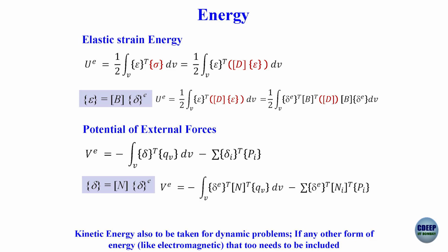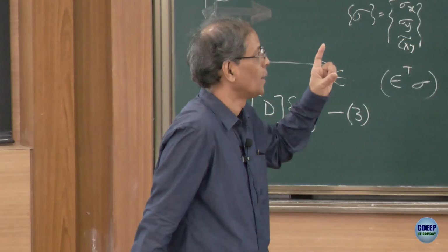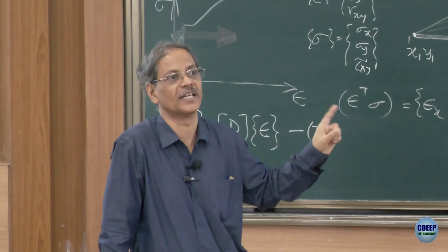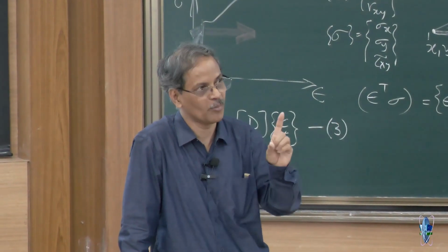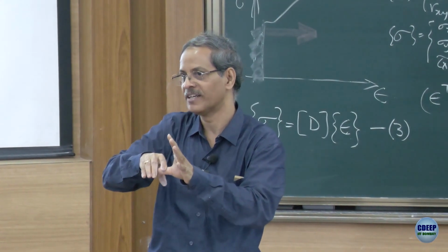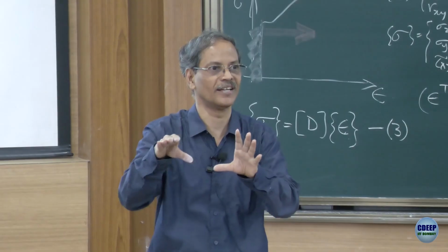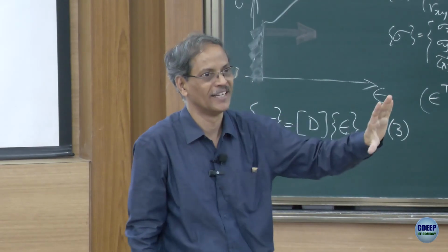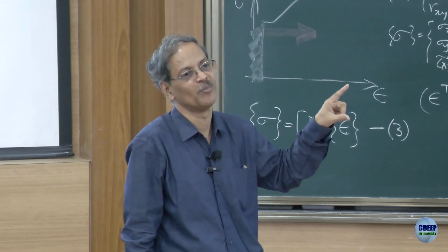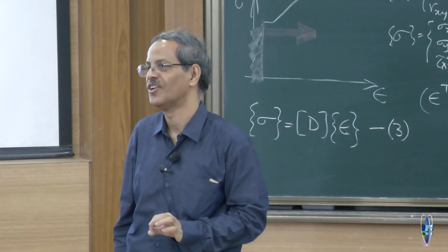Or you got 5 on 30, you are very bad, what is this? So, it is a dynamic impact load, so you have to design it for that, right. So, then you have to take kinetic energy into consideration, which we have not taken into account in this case. So, for dynamic problems, next when I am going to introduce time domain, I am already preparing you for that. All this formulation will hold good, except that energy expression will change. It is not just a strain energy, but I have to bring in also kinetic energy.